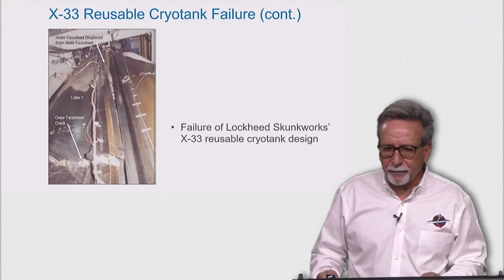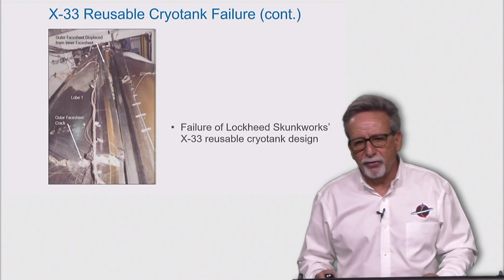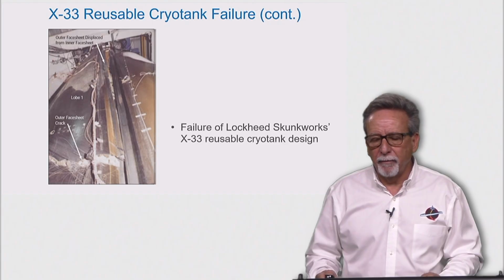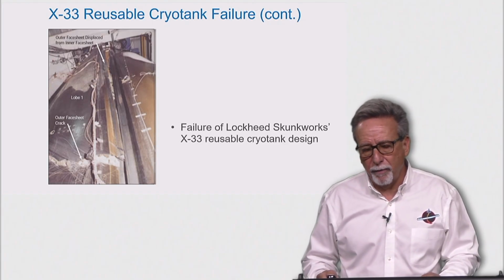Cryogenic temperatures either allowed the hydrogen to remain liquid within the cells or caused air or gaseous purged nitrogen to enter and liquefy by the process we identified earlier called cryopumping.